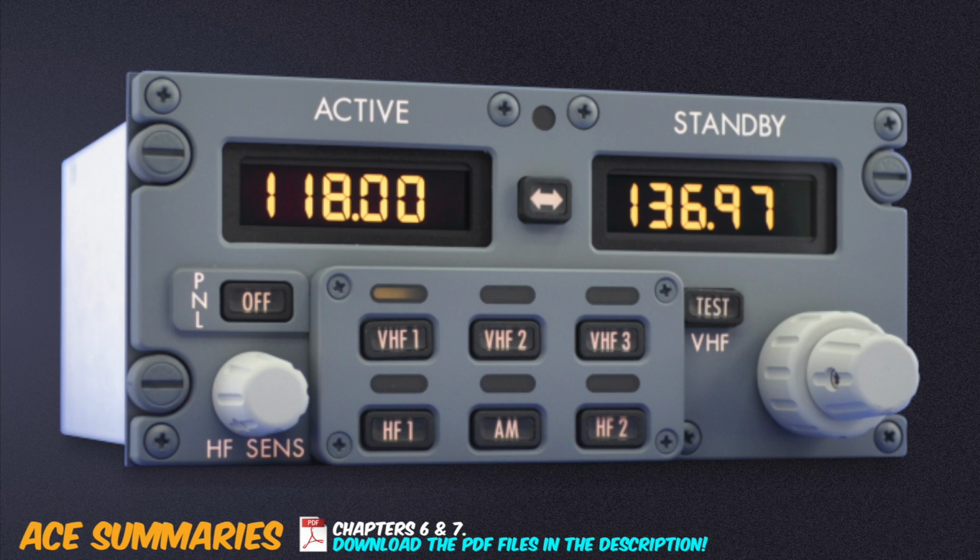Now let's move on to radio communication systems. VHF is used for short-range transmissions using line-of-sight propagation. Range is affected by the transmitter power, the frequency, obstructions, as well as fading. The line of sight of VHF communications can be calculated using 1.25 times the square root of the height of the transmitter plus 1.25 times the square root of the height of the receiver. These heights should be measured in feet above mean sea level.